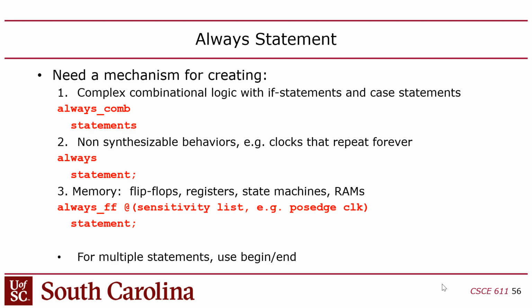But there is still another way that you could make a latch, because I could do something like this. I could still put always com, which is supposed to make combinational logic. By the way, are you comfortable with that term, combinational logic? Combinational logic means anytime any of the inputs change, boom, the outputs update, because the output is only a function of the inputs. Whereas sequential logic is when you have some kind of memory in there, where the outputs are a function of the inputs, but also the historical old values, the inputs from the past, which somehow affect the present. That's sequential logic.